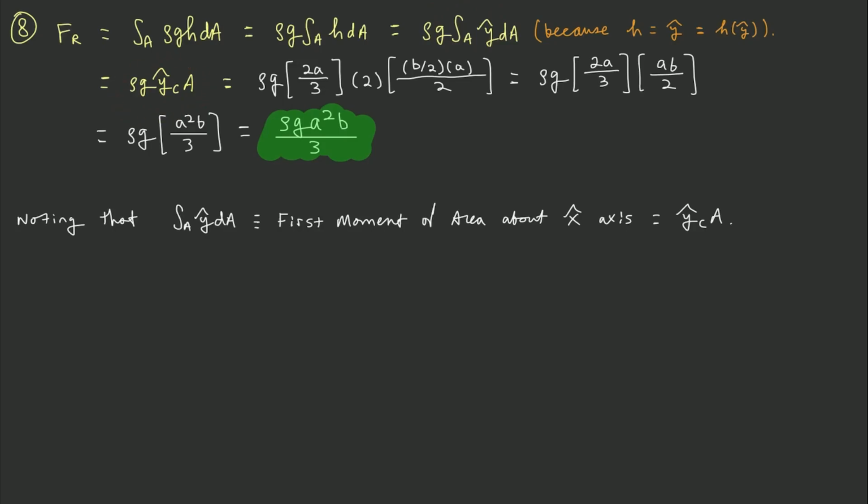And then we just need to know what the y hat coordinate of the centroid of that triangular area is, and we know what the location of the centroid is within a triangle. It is b over 3, h over 3 for a single right triangle. We extrapolate that to a double right triangle, so to speak, a full right triangle, and we get this final